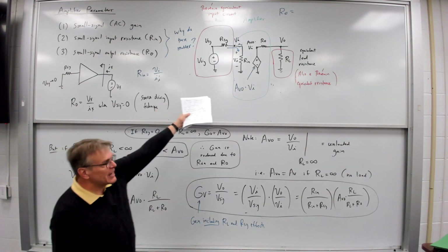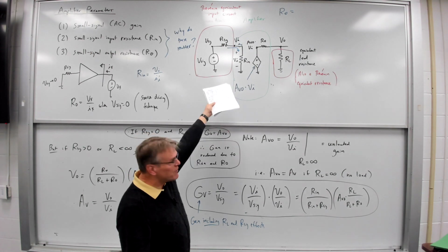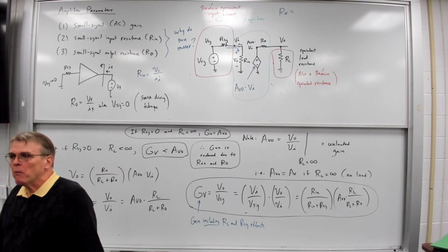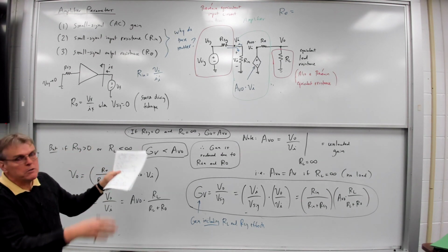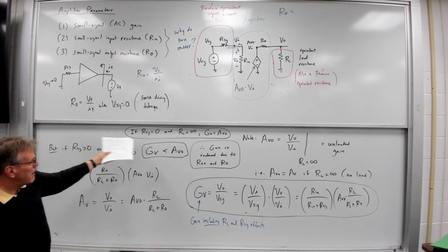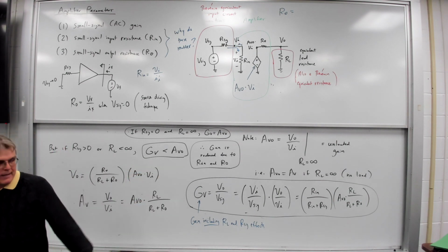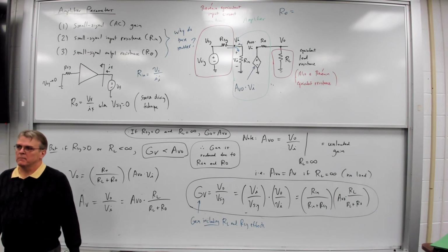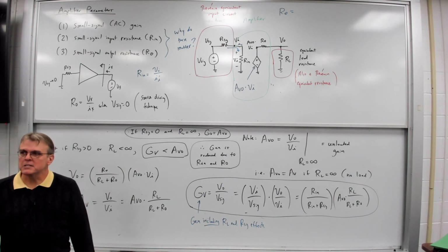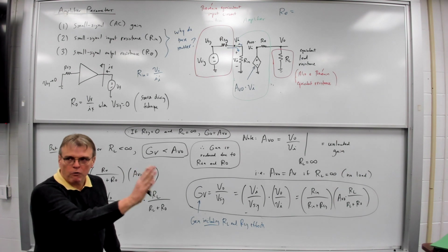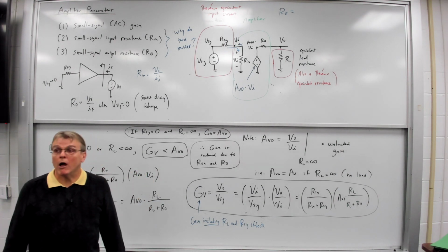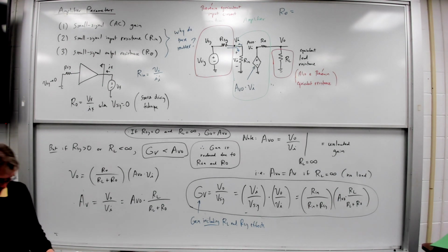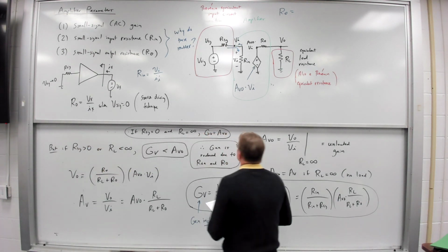And unless I can build an ideal amplifier with infinite input resistance and 0 output resistance, which we can't do, then connecting a load resistance and an input signal source absolutely impacts the value of the gain. And that equation describes how it works. That's why we care about Rn and Rout. Because as we're going to see, the input resistance and the output resistance will affect the overall gain equation. They will lower the effective gain that's possible because of those effects.